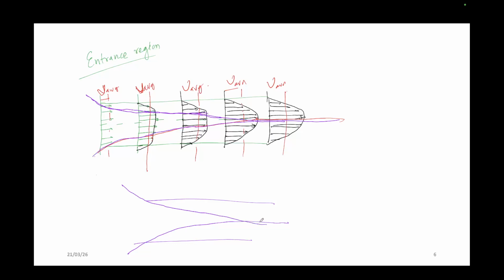After a certain distance, both boundary layers reach the same value. Up to this point, there is a boundary layer change, and the velocity changes as I have shown here. There is a sudden change in the velocity profile, but as you move further the change is in a uniform manner, gradually increasing in this region, and after a certain distance there will be a fully parabolic profile.